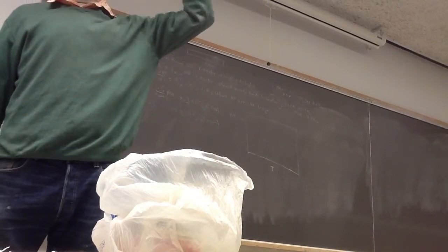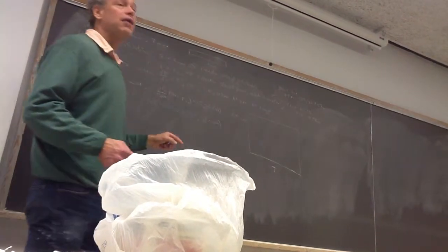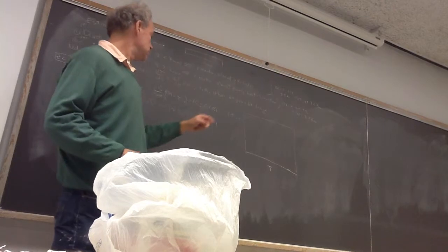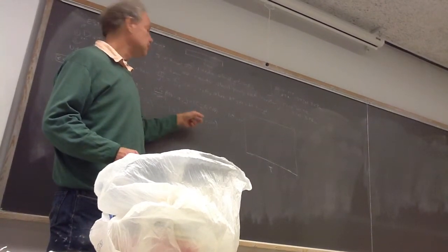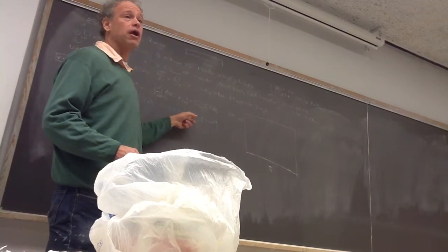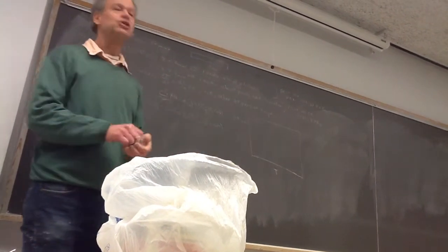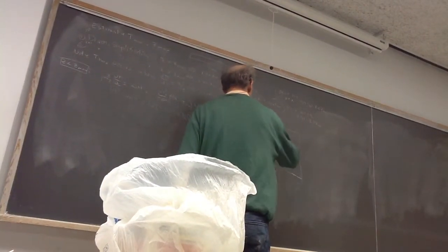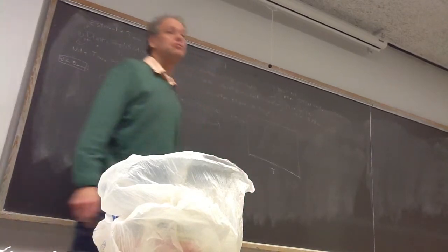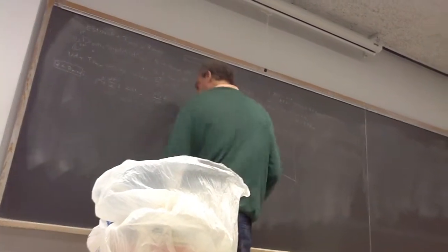So it starts going up nearly exponentially. And then when I go way down the reactor, there's no C left. K is very high because T is high, but there's no C left. It was adiabatic, so I know it's got to come back down. So I know immediately that the curve has to look like this. It's got to go up, and then it's got to go down. Let me draw it again.